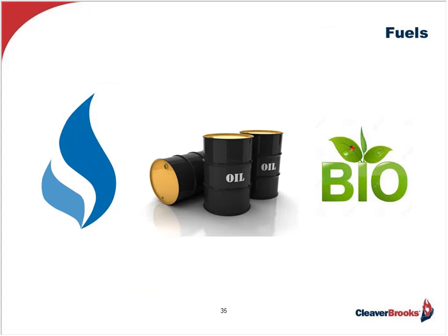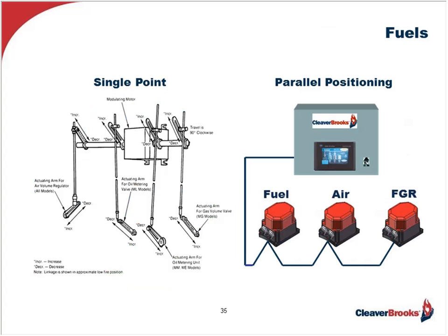As far as fuel firing is concerned, the Firetube boiler is quite versatile. It's able to handle an array of fuels, including the standards, natural gas, propane, light and heavy oil, and then, of course, the biofuels, too. Now, this would include landfill and digester gas primarily, but also fats, waste oils, and greases coming off various processes. And as such, these are all renewable.